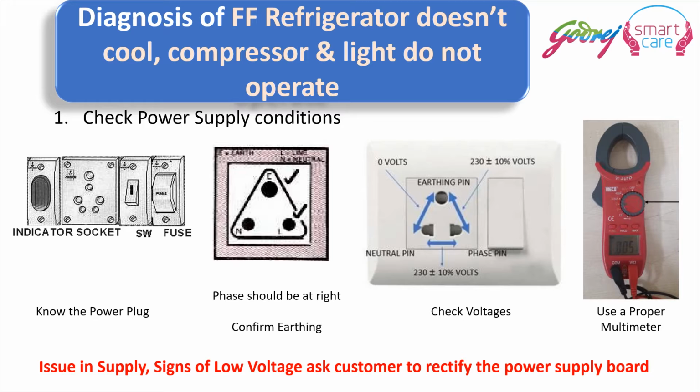Neutral to earthing voltage should be 0 ideally, or at the most 2 to 3 volts AC, but not more than that. Phase neutral and phase earth should show somewhere around 230 volts plus or minus 10%. Use a proper multimeter to check these voltages and note it down.